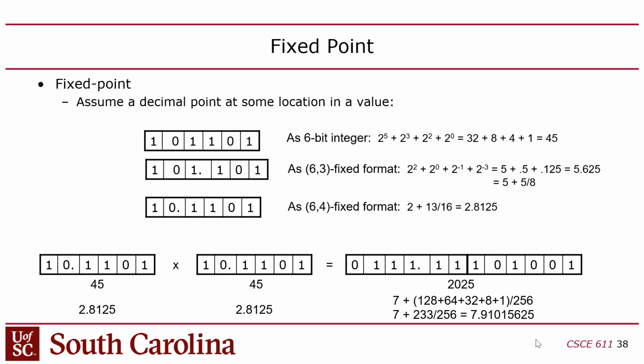So if you have a fixed point number that's 32 bits, you might say, oh, I have 32 bits of precision. No, you don't. The number of bits of precision depends on the number of leading zeros in that register. So if you have a 32-bit number and you have 30 leading zeros, there's only 2 bits of precision there, right? So that's a downside of fixed point.